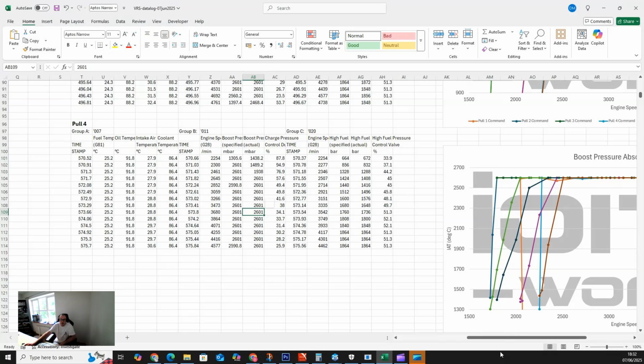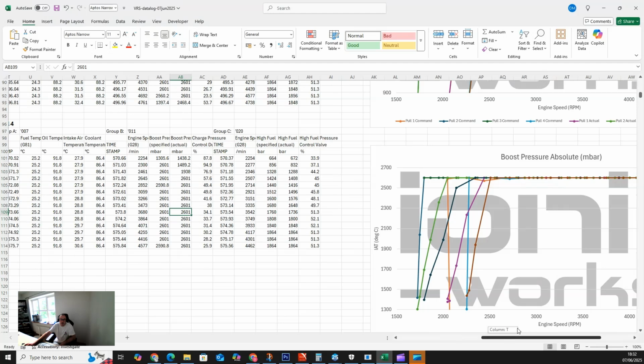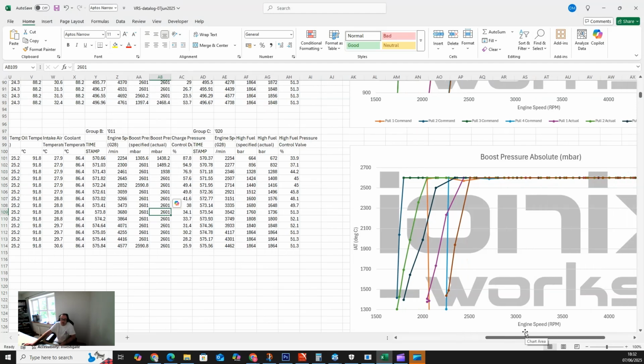Would you not expect it to go up to 3000? The sensor calibrations, we'll look at this in a minute. As far as I remember, I'll double check that now here, but while they do go to that value, the typical calibration used in the ECU is lower. And I know from experience that it's not uncommon to see a value like this as your peak